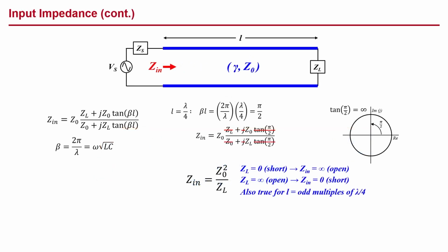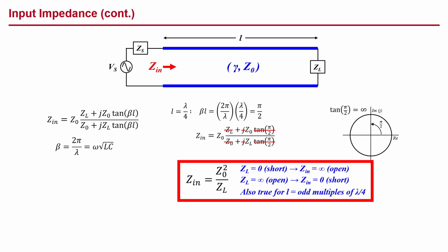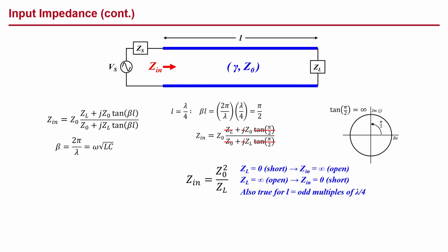So, at these quarter wavelength resonances, the impedances are not what you think they are, and your circuits will not behave the way you think they should. But being aware of the physics can help you quickly diagnose and address any of these behaviors when you come across them. And that's when and not if.